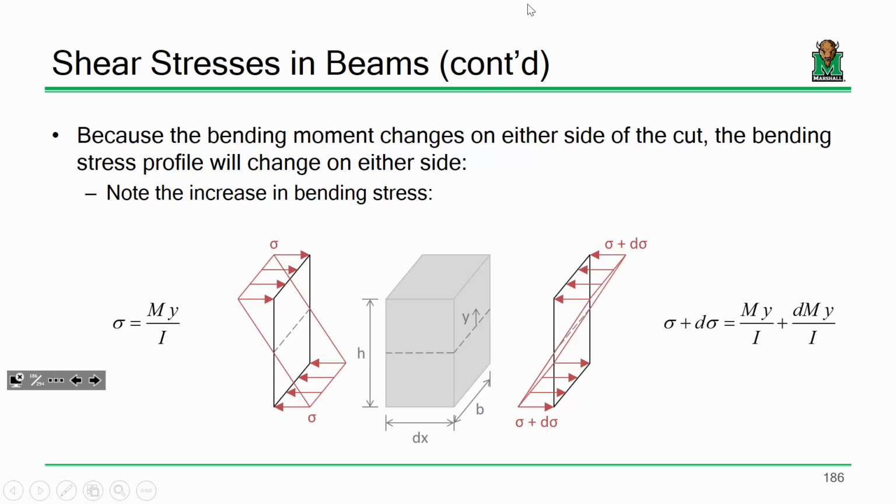So here's that little differential element, and I'm looking at it in 3 dimensions. This is that little slice. I cut the slice out, pulled it out, and I'm looking at it. So let's diagnose what's going on here. The little slice is dx thick. Now if I samurai sword or lightsaber through the section and look at the beam, what do I have? It's b wide, h tall. For now, I'm keeping this restricted to a rectangular cross-section. So what's this dashed line right here?